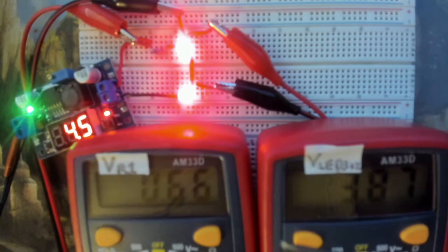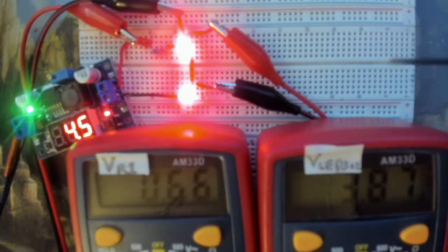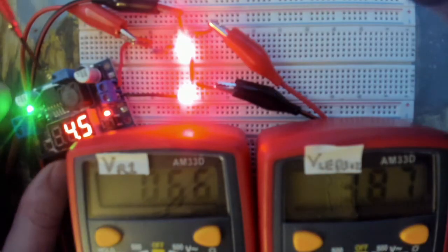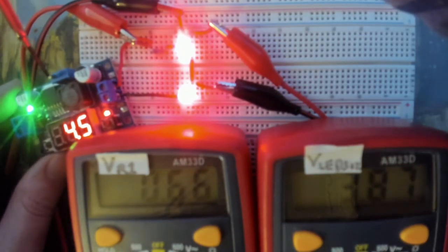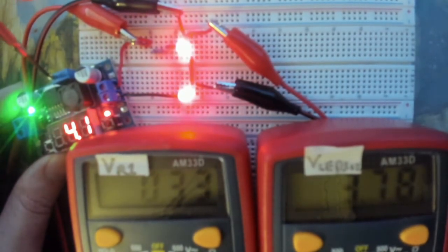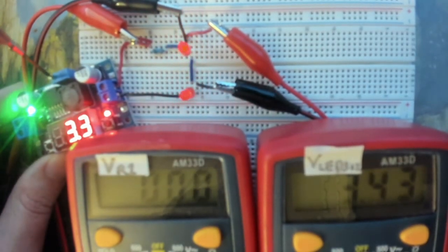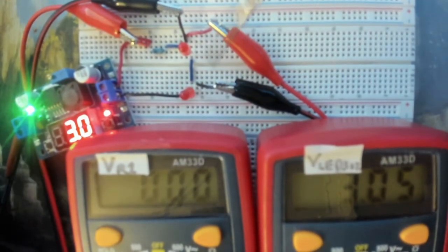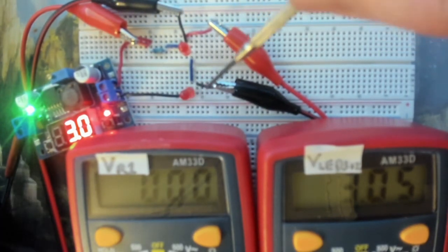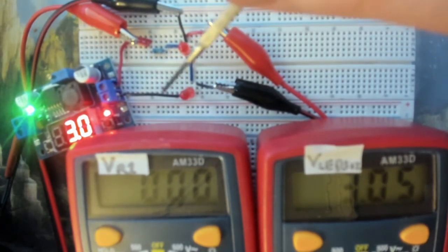Now, one thing that this model is good at showing us is that as I lower the voltage across the circuit at our source down to 3 volts, you'll see that the LEDs get dimmer, and right around 3 volts, we no longer have enough voltage to keep both of our LEDs on. Now, this isn't because there's no current going in the system, like in our model that we showed. There's just not enough current for the LEDs to be emitting light that we can see.